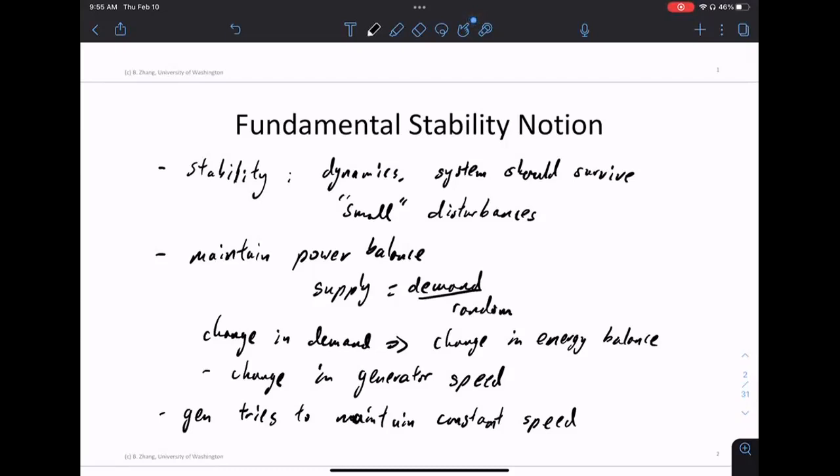I will not say it that way. No, I will not say we'll have bad inertia, right? The reason is, I would say it's a more challenging problem. The reason it's more challenging is because this changing demand shows up as changing speed. This is governed entirely by the conservation of energy. So nature is helping you out in that regard. Where is your energy stored? It is in the rotating masses. They have to respond to this.